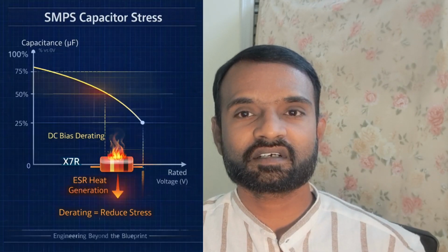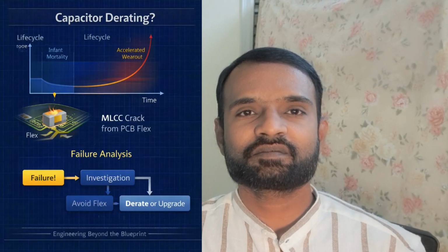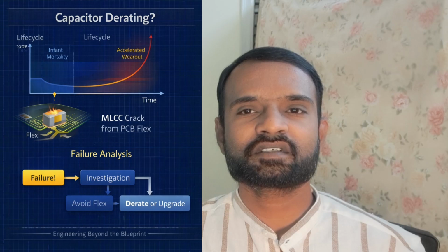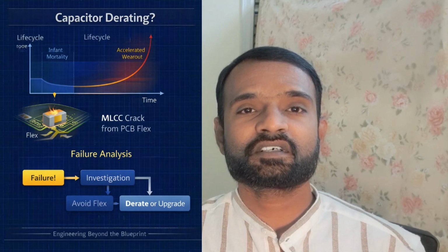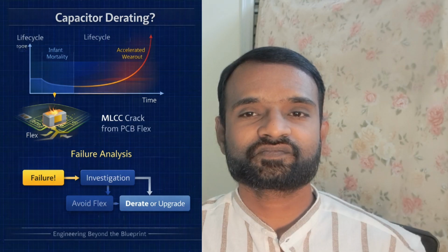Next comes, what are the electrolytic failure modes? The answer is sometimes the capacitors dry out and leak, and ESR increases. Example, old SMPS fail due to dried capacitors. Why does MLCC sometimes get cracks? The answer is PCB flex and thermal stress. When there is thermal stress, obviously the MLCC is going to crack. Use flexible terminations for MLCC.